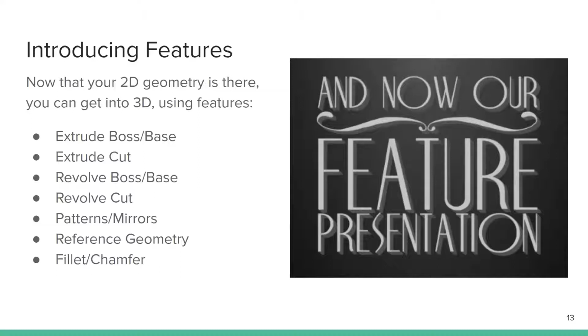And then you can also make reference geometry. So say if you want a new plane to be offset 2 millimeters from one of the faces of your cube, you could do that with the reference geometry tools. You could also make an axis that runs straight through the center of your cube, parallel to one of the edges or something like that.